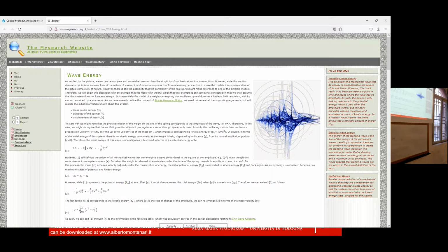So it's a movement parallel to the shore? Yes. Like I stay here for 1 year. I'm sitting here, and what I see is a volume of beach passing on the beach. Which means that if you place a groin here, you may expect during 1 year to get 1 million cubic meters accumulated against the groin. And downstream, it means that you don't have any more flux and you may have erosion. So I anticipated what is the effect of a groin. You have accretion upstream, I should say updrift, and downdrift, you have erosion.